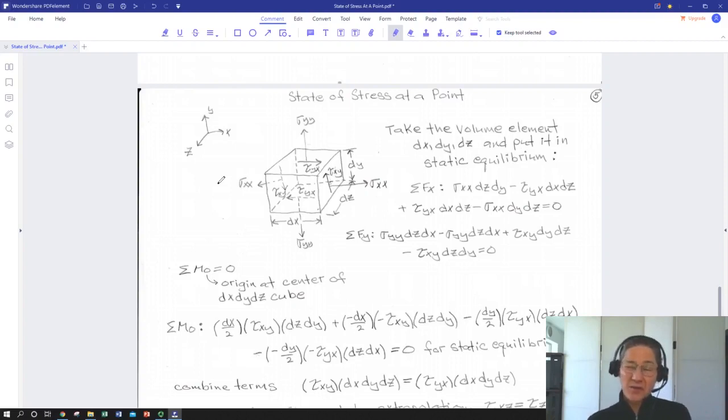And as you can probably guess, things in plane strain, where you can by definition have stress in every direction, tend to happen in the middle of things. When we get to the strain section, we'll take a look at things that tend to be in plane strain. Those real life aspects of plane stress and plane strain applications are important to recognize, to know when we could make that approximation and when it would likely be valid, because it simplifies our life quite a bit from a calculation standpoint.